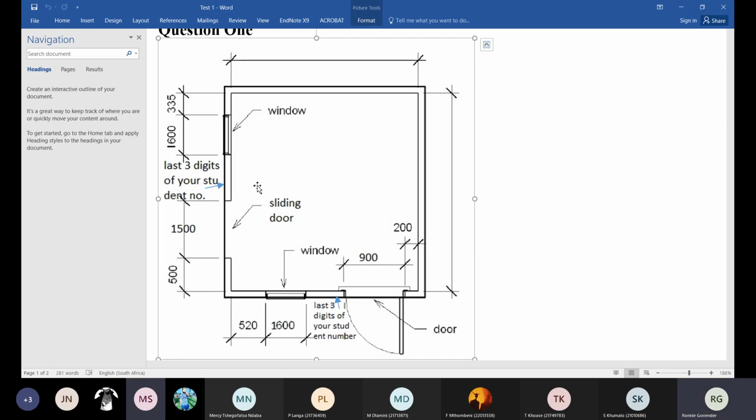Sorry, did we add brick force to the gable also? Yeah, I told you. You would have worked it out. The easiest way to work out for the gable is by similar triangles. Right, you have to add for the gable. The only time you don't add for the gable is internal walls, because internal walls don't go up to the gable. They go up to the ceiling height. But external walls, your perimeter walls, you have to add for the gable, right?